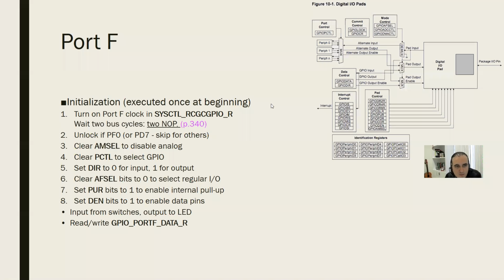We were discussing the first step of the initialization, which is turning on the clock signal that is being fed to the digital port. And from the datasheet, we've seen that without feeding a clock port, we won't be able to change anything on the control registers, which makes sense.